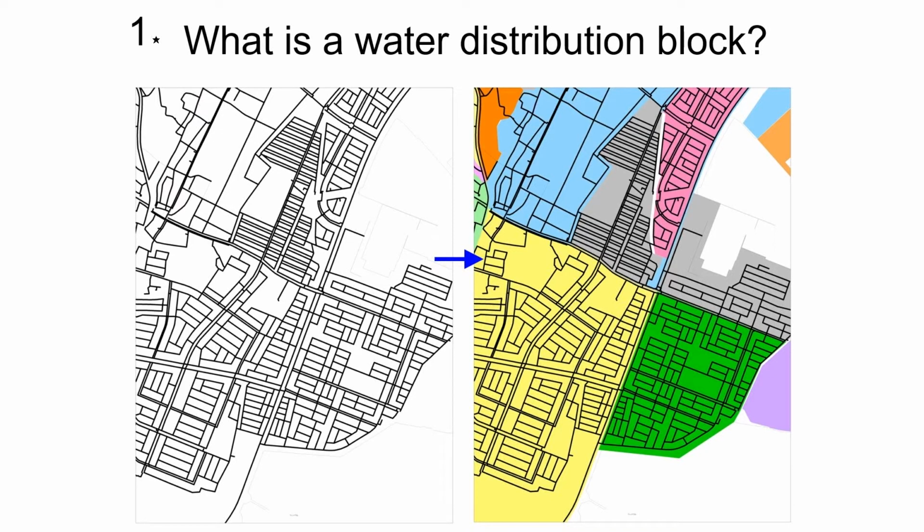The use of those blocks is advantageous on 3 points. First, it enables improved operation and maintenance by identifying the amount of water distributed as well as leaked. Second, by organizing water flow, it helps minimize pipe damage from disaster or accidents, as well as repair work required.